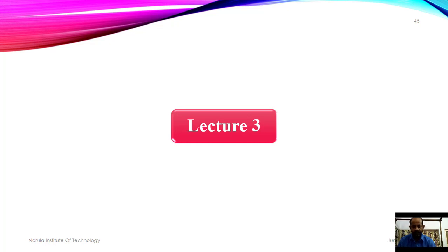We have also mentioned 2 different theories, one is called double revolving field theory, and another one is cross field theory. These 2 theories explain the working of single phase induction motor.